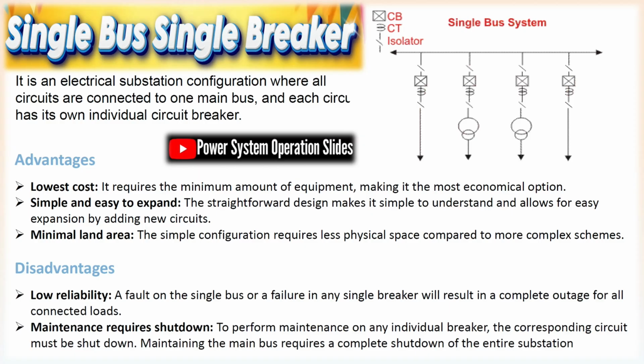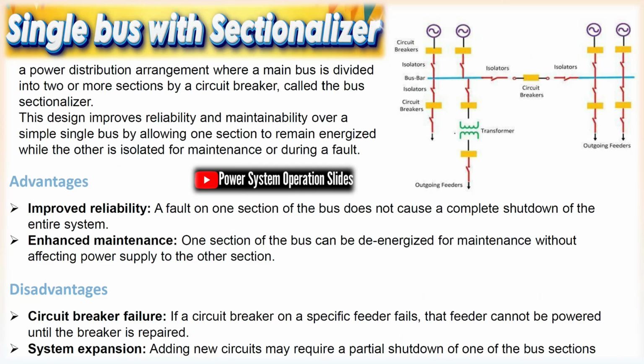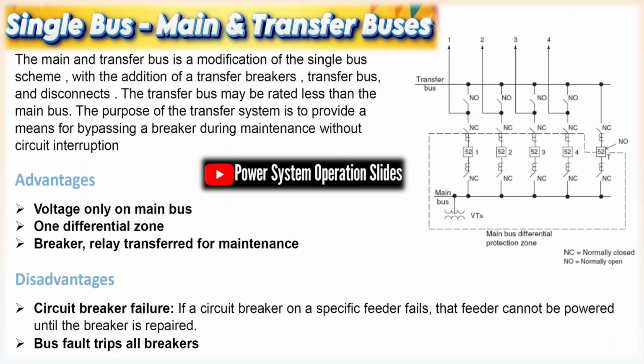Current transformer, CT. CTs step down current for metering and protection while maintaining proportionality. They isolate secondary circuits and feed relays and meters. CT secondaries must never be left open when primaries are energized.